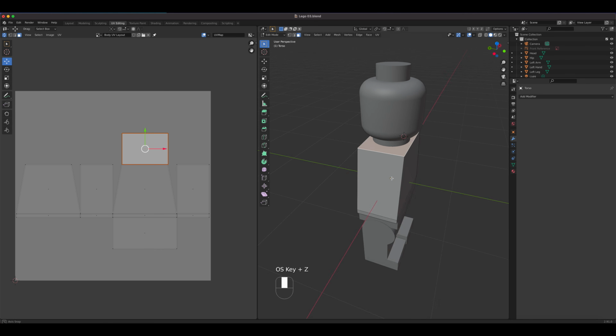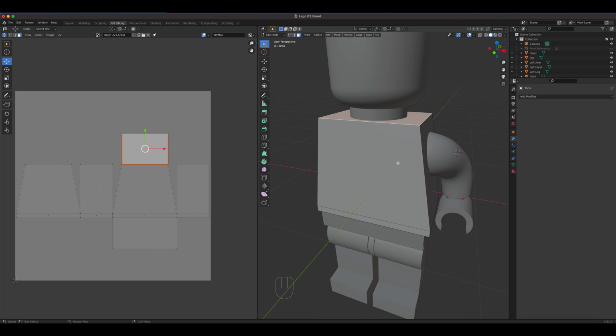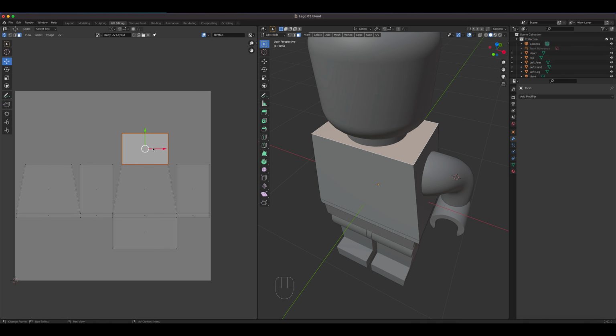So let's say you're trying to do a Lego texture with overalls, right? So you want those straps going like this. That's kind of hard to match if this thing is away from here and it's a different size. However, in Substance Painter or even Blender's texture paint, you can actually paint on the model. So it doesn't matter how big that is or how small this one is. If you're just painting here, it will connect. It will compensate here when you draw it out.